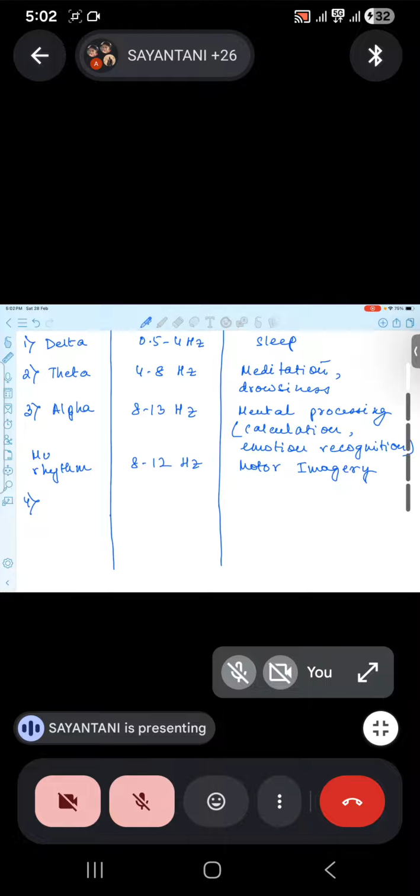So if a subject has lost any one of the arms, the subject cannot physically move the hand, right? So what can the subject do? The subject can mentally imagine that he or she is physically moving, say, the left arm. He has lost it, but the brain signals are active. The arm is missing, right? So if he or she is imagining the left hand is being moved, then I can capture the signals, that is the motor imagery signals, classify them or perform clustering, feed the output to a robot, and the robot is going to fetch the glass of water and so on. Okay, so this motor imagination part is very, very important.